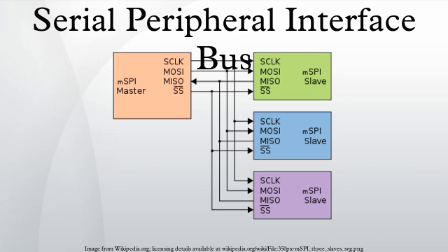Operation. The SPI bus can operate with a single master device and with one or more slave devices. If a single slave device is used, the SS pin may be fixed to logic low if the slave permits it. Some slaves require a falling edge of the chip select signal to initiate an action. An example is the Maxim MAX1242 ADC, which starts conversion on a high-to-low transition.